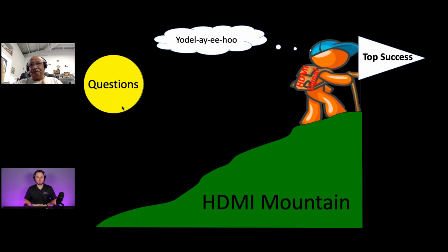I could tell you right now that you could never take a system that's demanding a 600 pixel clock and give it 300. It'll never work. And we have that here in the lab in a way because of our equipment. Our equipment has a separate system clock, and to give you an example, the system clock is 181 megahertz for one particular frequency. If that's 181.4, I lose sync.